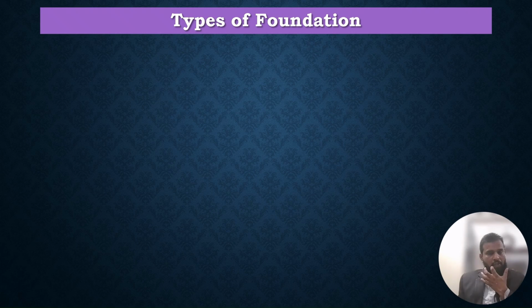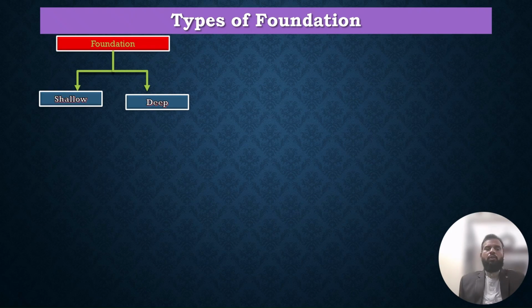Now coming to the types of foundation. Foundations are broadly classified on different bases depending on the purpose of study, but broadly they are classified as shallow and deep foundations based on the dimensions of a foundation. A shallow foundation is one where the width of the foundation is greater than the depth of the footing; then it is known as a shallow foundation.